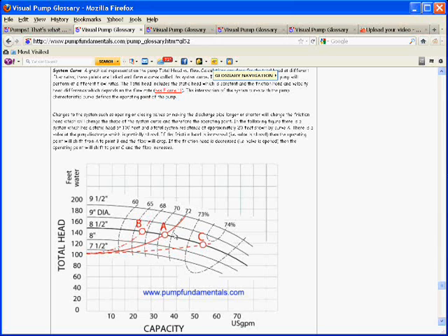So the range that's available to me on this pump is to follow the system curve all the way up till I get to the maximum impeller. It means I have to change the impeller, of course, so that's kind of awkward. What we often see nowadays is that the pumps are fitted with variable speed drives, so that you can actually change the speed of the pump at any time you wish, or even control it automatically. So these curves then, instead of having impeller diameters, they would look exactly the same, but these curves would all be different speeds. So this might be, I don't know, 800, 900 RPM, 1000 RPM, right?